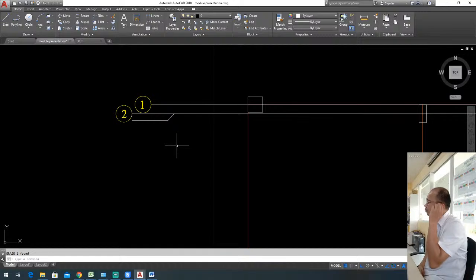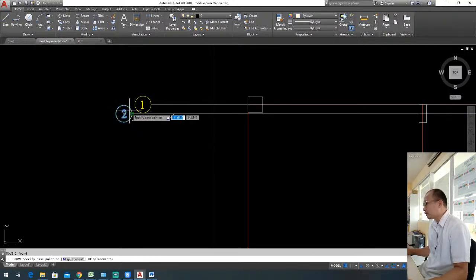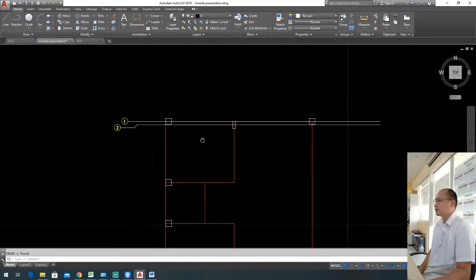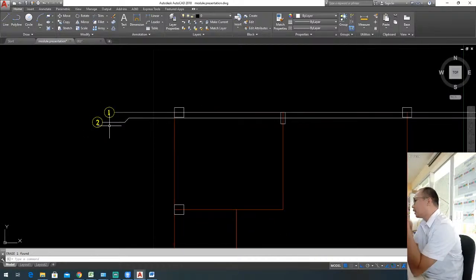But if it is much too close, there is a tendency that this line right here might be intersecting this line right there. So you may use this procedure. The important thing here is that this would provide an idea, when you are going to do the stakeout already on the field, that there must be a line right there, because it would hit a certain column. There should be a nylon line there because it's going to hit a certain column. So that's the thing.